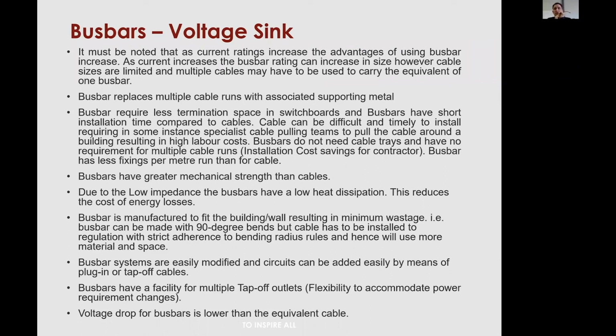But as soon as you have 2 or more batteries or MPPTs, solar chargers, or inverters, you must go with a bus bar. The bus bar is the biggest and most powerful way of synchronizing your DC system.